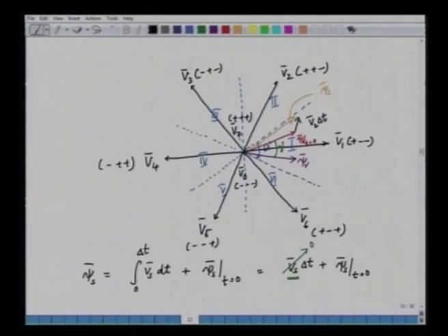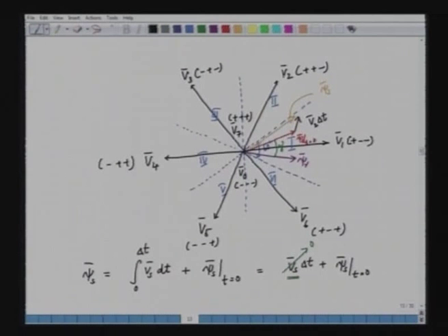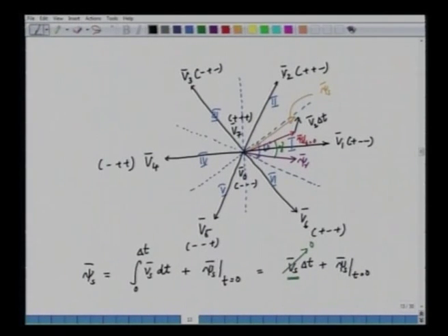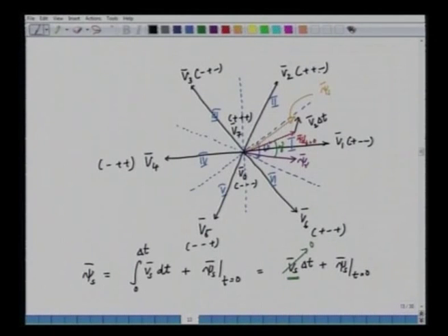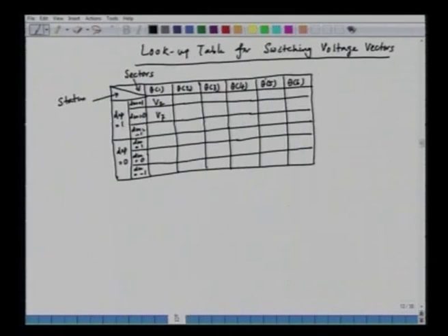We have two 0 voltage vectors, V7 and V0, and we applied V2 a little earlier because we wanted to increase the torque and increase the flux. Now, we want to keep the torque as it is. So, from V2 it is easier to switch to V7 than V0, because V2 is plus plus minus, and if you switch to V7 it is plus plus plus. So, there is a change of only the switches of one leg, that is the C phase: the upper switch is turned on and the lower switch is turned off. So, to avoid the minimum number of switching, we will have V7 here.